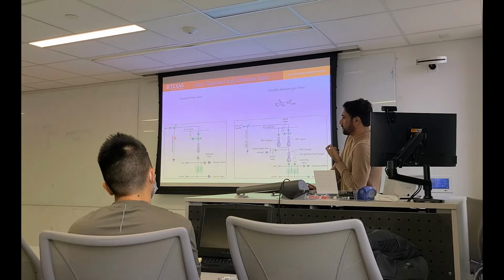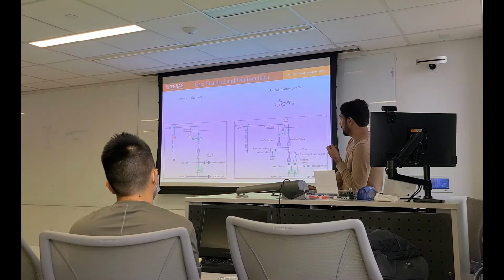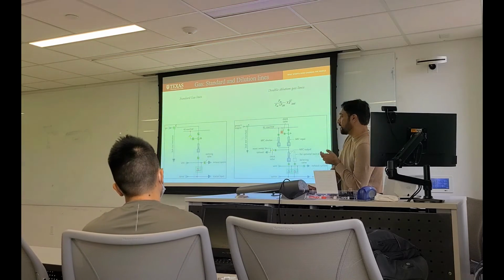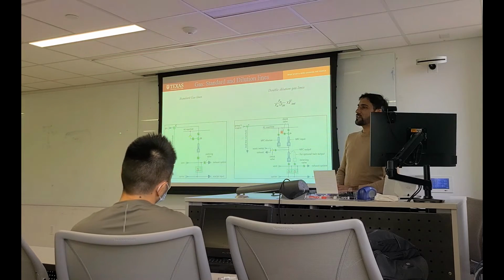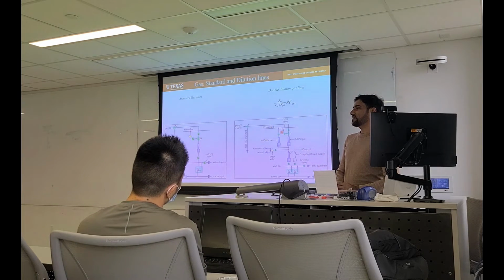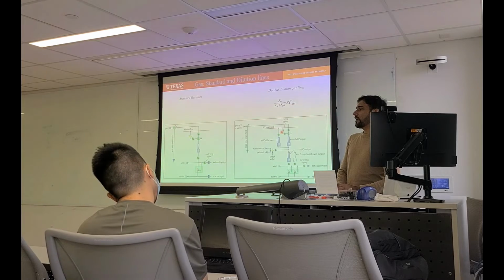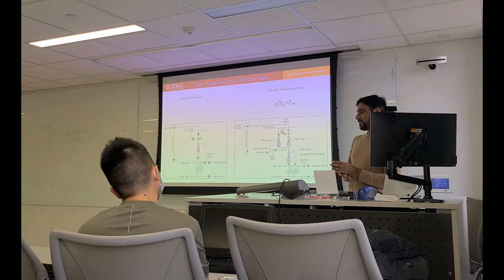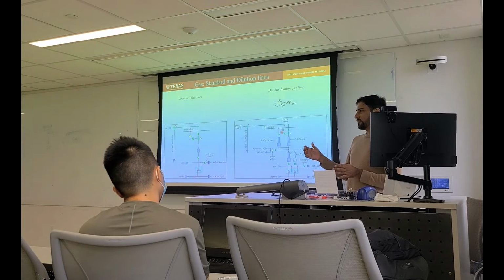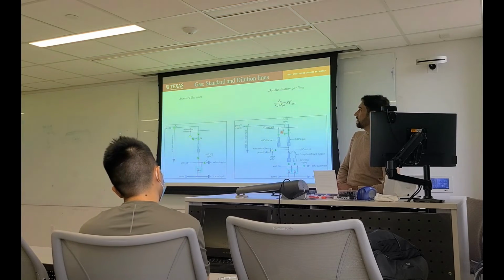This is very simple. You just flow whatever gas you need, and you get gas inside the reactor. Why do we need dilution? Because for xylene, we need only a few SCCM. I was using 1.5 SCCM, 2 SCCM. In that case, you cannot directly flow 2 SCCM because your flow will not be uniform. So you need to dilute it with the carrier gas.